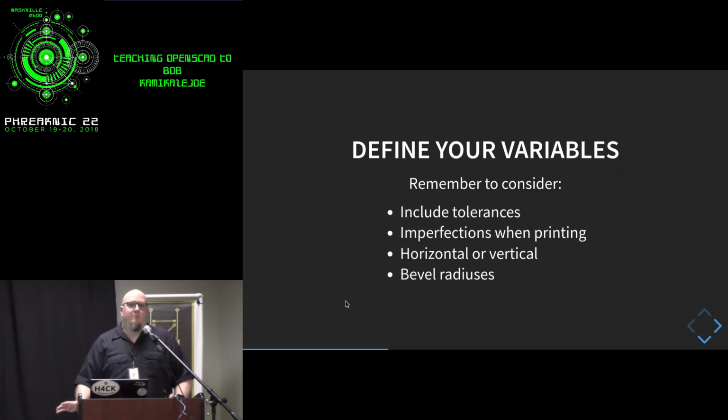Another thing to remember is be mindful of curves when you're trying to smooth out corners. Eventually you're not going to want sharp corners on everything. Having nice little curves makes things look nicer. And when you have a little gadget in your pocket that you printed, you're not going to want to jab yourself in the leg with a sharp corner. So when you add a little curve, you end up actually adding the radius of that curve to the object. That's something you need to keep in mind as you get deeper into this.